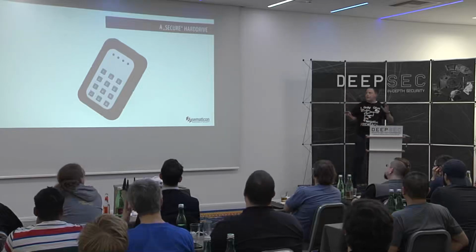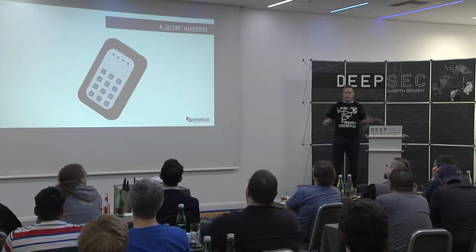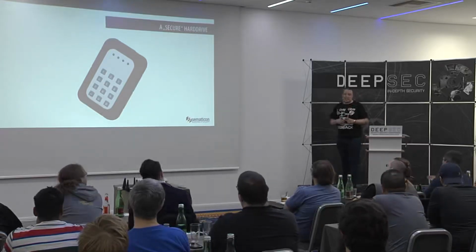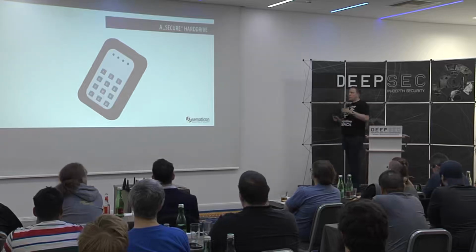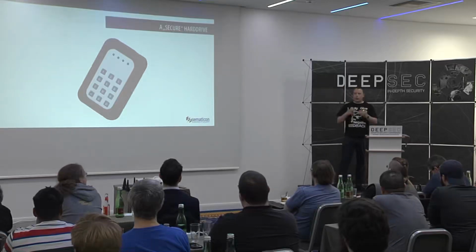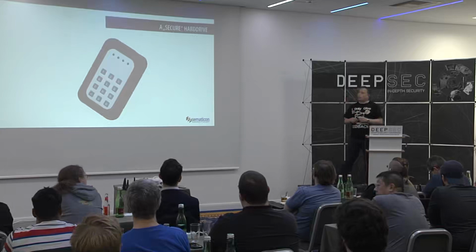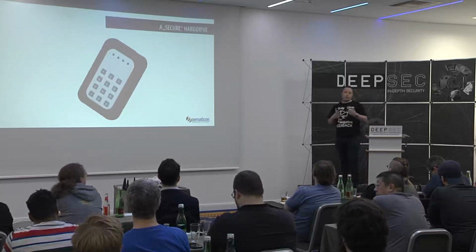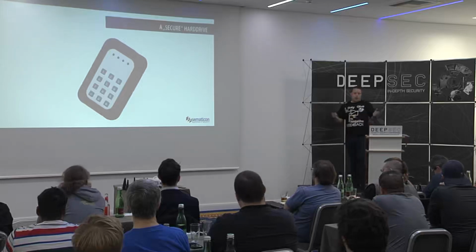So at the very end, what I'd like to tell you is that keys in hardware is always good. You have a reliable service outside that is probably tested against these attacks, but please have a look in the manual to see if that's really the truth. And you can be sure that the crypto algorithms are implemented the right way. There are certifications for this process to make sure that an AES implementation really works for all ciphertexts, not just some, and to make sure that all your keys are created in a secure way by having a true random number generator. So keep keys in hardware, take care about keys in hardware.